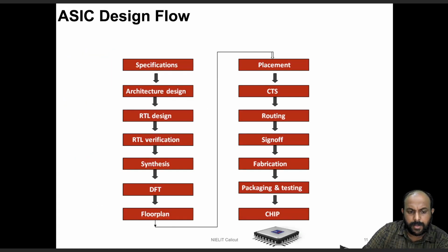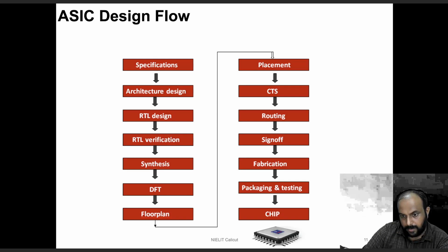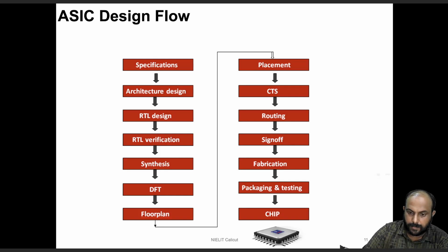you can see here, including synthesis, DFT, which stands for design for testability insertion, floor planning, followed by placement, and CTS, which here stands for clock tree synthesis. It is followed by another step called routing, then design sign off or design verification, then fabrication, packaging and testing.